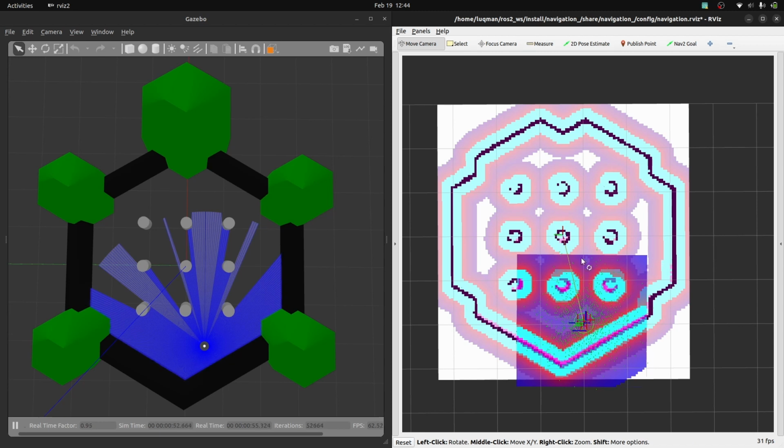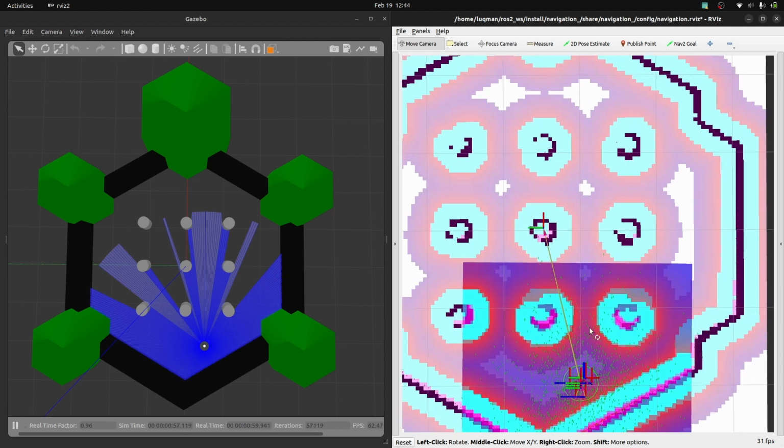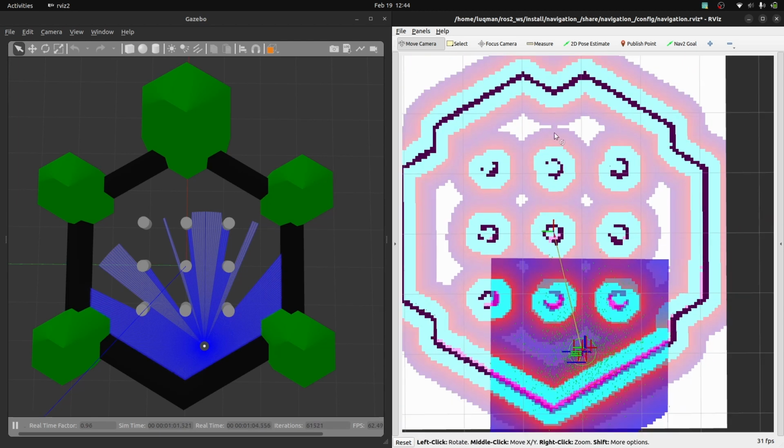These things are actually from the parameters we have. Now we have told the ROS simulation that our robot is at this specific point, and now you can understand where this whole map is. This whole map is obtained from the map we saved. Now let's do the autonomous navigation part. I'm going to click this Nav2 goal and give it a certain free area, that is this white space. I'm going to put my arrow and give an orientation as well. Let's make it look at this specific point.